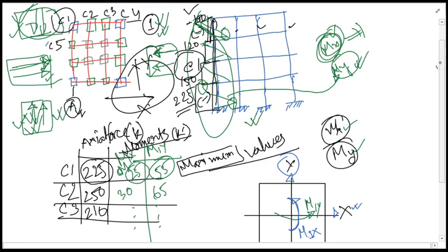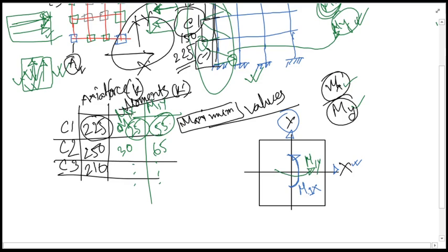So if you ask, okay, why can't we take the maximum axial force and design all the columns similarly? But no, in these cases there is a problem, because although the axial force might be greater in amount, the moment might vary, and therefore the design of the column might not be governed by the maximum axial force all of the time. That's why you will have to satisfy your column section for all of the columns.